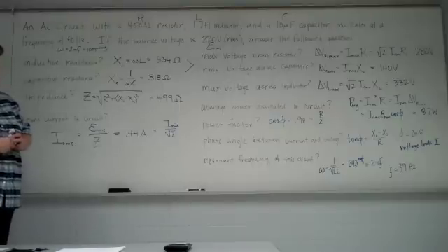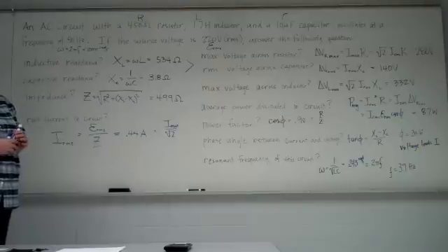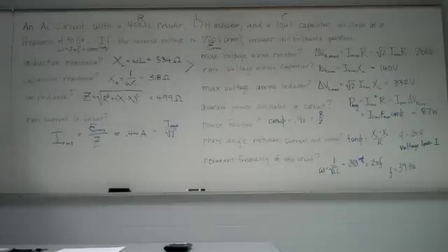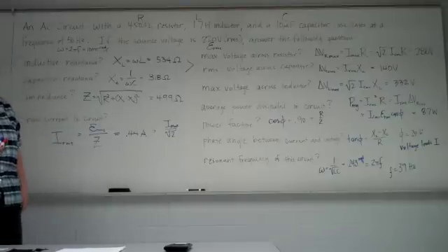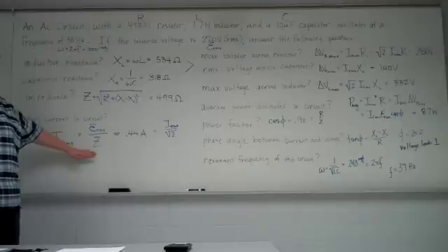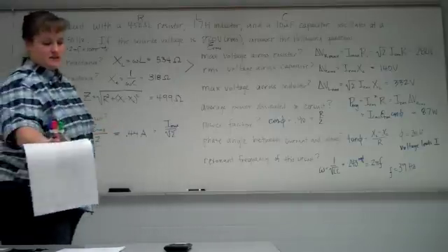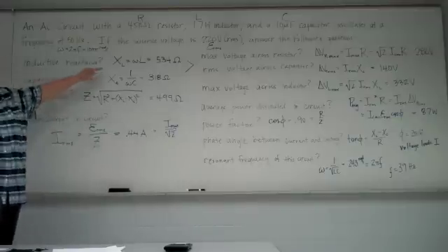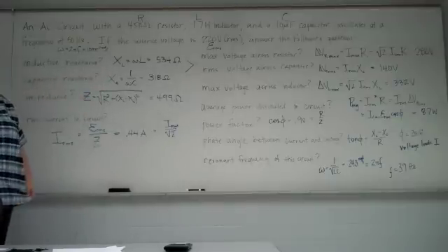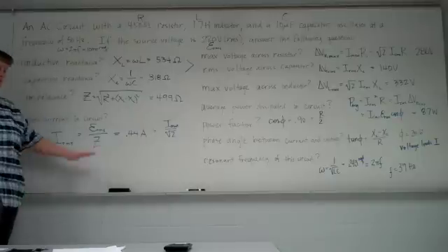So, in a nutshell, this is what we've been learning. On the test, I'm not going to ask you 12 different questions. I may ask you for current, for example, and maybe one of the voltages, and maybe some power. But please keep in mind, to get the current, you needed to figure out XL, XC, and Z. Those were required. So even though I may not explicitly ask you for XL, XC, or Z, you may very well likely need to find them to answer the other questions.